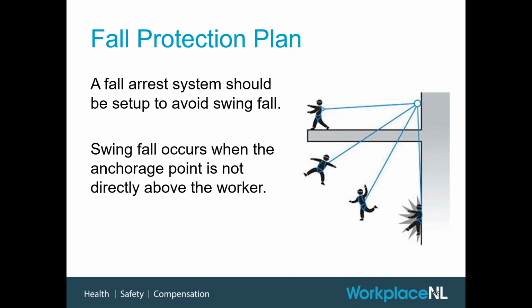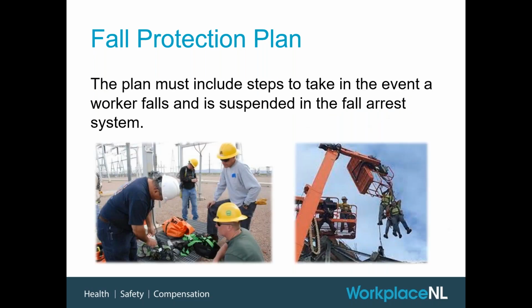You're basically pulling your anchor along the line as you go, so that you can keep it close to your body, so that if you do fall, you can avoid this swing scenario. We talked again a little bit earlier about the importance of having that plan in place to rescue someone if they've been suspended. So again, that is required if you're using fall arrest, and these types of rescue plans really